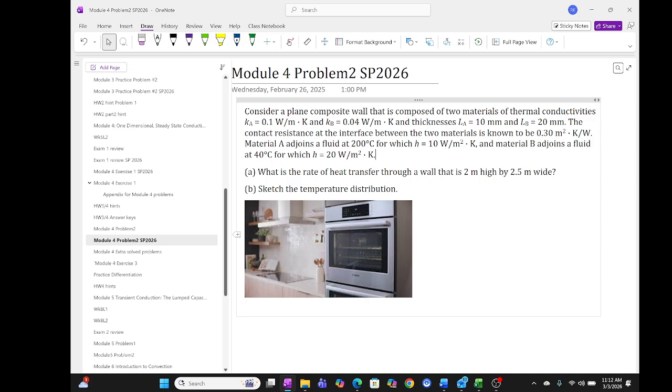There is a thing called thermal paste. Anybody heard about it? Okay, so you can put some thermal paste, and then still push it so hard, right? Those microscopic gaps are going to be filled by another solid. That's the thermal paste, and it could be very minimal, but it still is there. There's no longer any air layer in between. That could still be here and there.